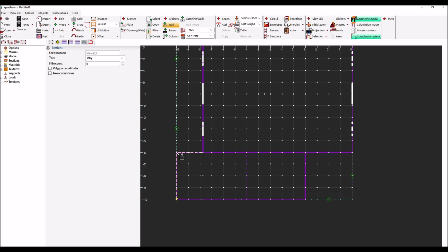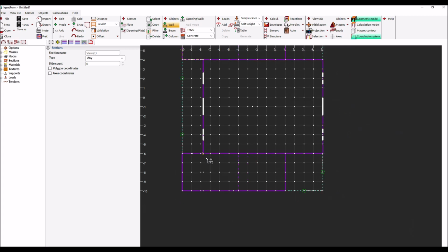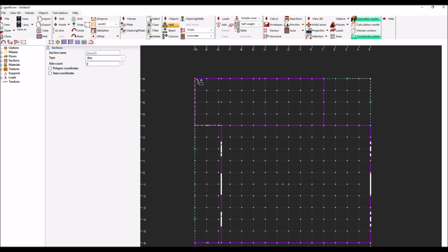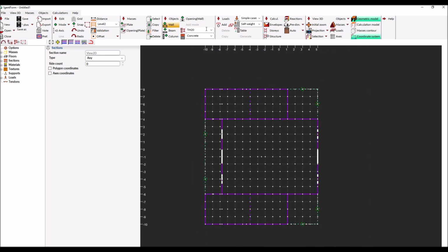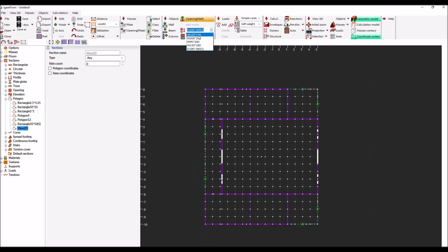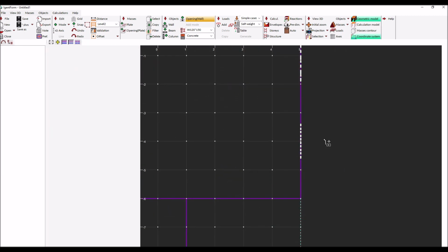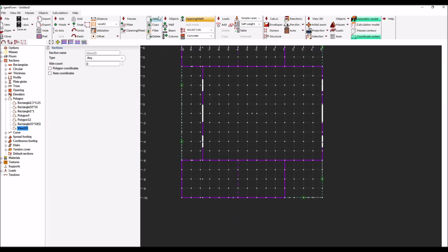Also here, display in previous level is very helpful during definition. As previously, polyline mode can be switched on or off depending on need. When any element is changed or added to section database, appropriate combo box controls are automatically updated in parameterization window and graphic menu. When, for example, during openings definition we change section, it automatically becomes a default section for next elements. A few openings have been added and our sample model is finished as far as geometry is concerned.